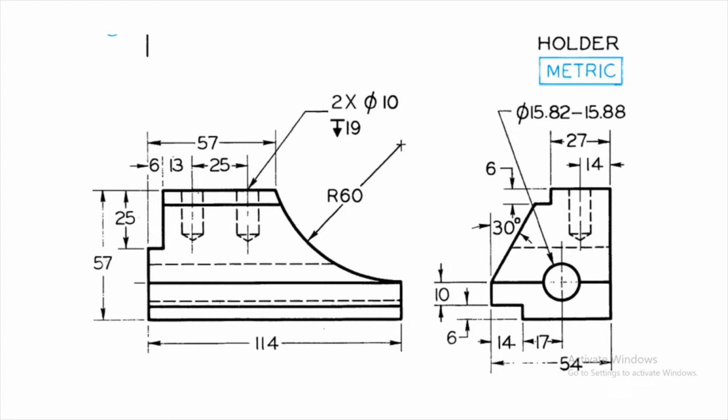Let's see the modeling approach in SolidWorks. When it comes to making the model in SolidWorks, you can start from either the front or the right. In this case, we can begin with the right side. I would prefer starting with the right side, making a closed contour for the overall shape of this part, extruding it completely, and then trimming out the extra regions to get to the final shape. This is the top to bottom approach that would be adopted in SolidWorks.